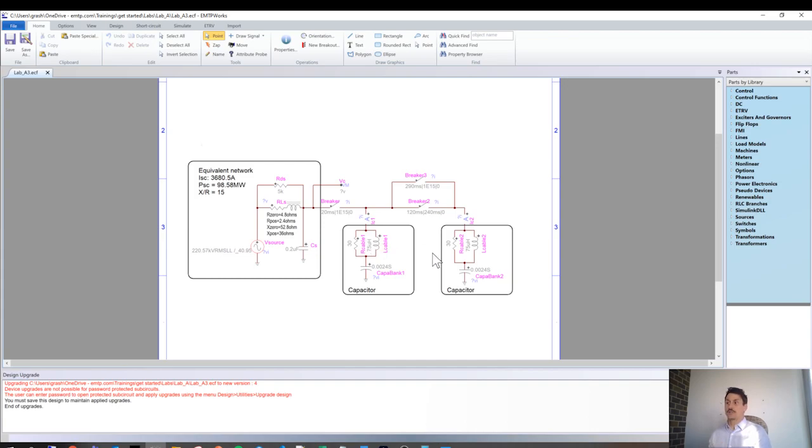It's very similar, actually, if you have a fault close to a capacitance, that's what we call the outrush. Then you have the same thing, an RLC circuit with the capacitance, the fault to the ground, and a very small inductance. So very high frequencies, even higher than the back-to-back switching, and high current magnitude.